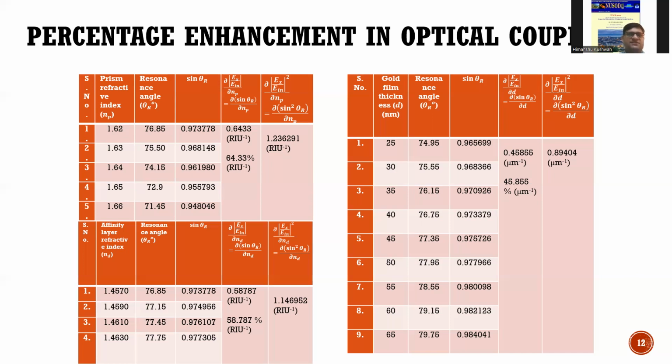The improvement in the sensitivity is the direct consequence of the increased real part of the effective index. With the increase in the thickness of the gold film, the real part of the effective index increases, whereas the imaginary part first reduces and then increases, with a minimum at around a gold thickness of 45 nanometer, which is in the range of skin depth of most metals at optical wavelengths. The propagation length depends inversely on the imaginary part, with the result that the propagation length of the SP mode is maximum at a gold thickness of 45 nanometer. That is why we have taken 45 nanometer gold thickness.